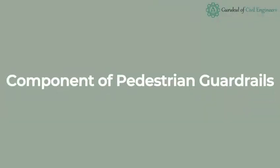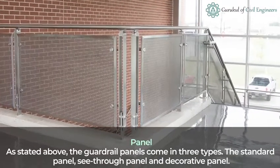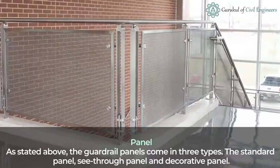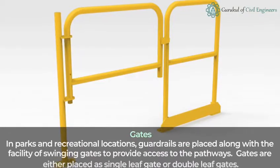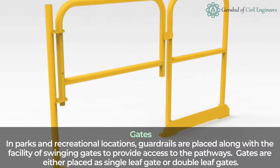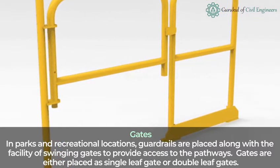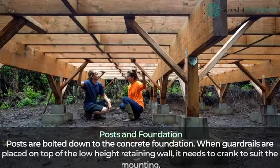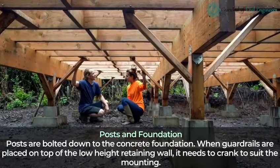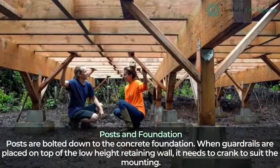Components of pedestrian guardrails. As stated above, the guardrail panels come in three types: the standard panel, see-through panel and decorative panel. In parks and recreational locations, guardrails are placed along with the facility of swinging gates to provide access to the pathways. Gates are either placed as single-leaf gates or double-leaf gates. Posts are bolted down to the concrete foundation. When guardrails are placed on top of a low-height retaining wall, they need to be cranked to suit the mounting.